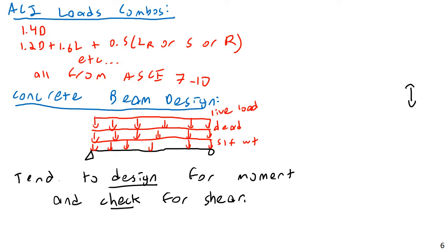So we'll design for moment and come up with an initial cross section. Then based on that, we'll assume an initial weight, come up with initial loads, and design a cross section. Then we see if that's adequate or not, readjust the cross section, readjust the loads, and loop around a couple of times until we converge on a value for thickness and reinforcement, etc.